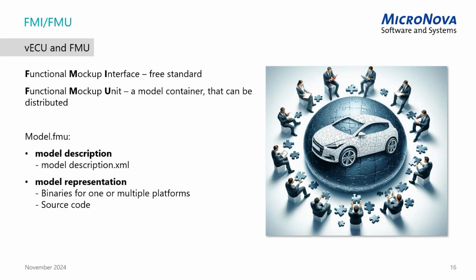For this situation, there is the Functional Mock-up Interface. It's a free standard that describes a functional mock-up unit, and this functional mock-up unit is just a container for your model. And this model could be any of one to three virtual ECU models. And if your tool supports this functional mock-up unit or this FMI interface, you are happy. You can just create this FMU and transfer it from one platform to another.